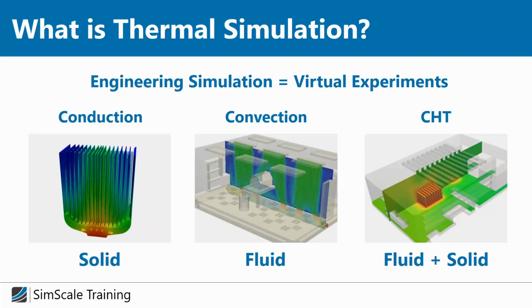And another simulation type, which is summarized under thermal simulation, is dealing with convection. And this one is very familiar with CFD, with computational fluid dynamics. And it's basically a CFD simulation, a fluid flow simulation, which is also considering the energy of the flow and convective effects. And for example, here in the example, you can see how a heating system is used inside a room. And the color here is representing actually the temperature of the air. And you can see how the hot air is entering the room at the floor, and how this hot jet is then spreading up and the air becomes cooler.